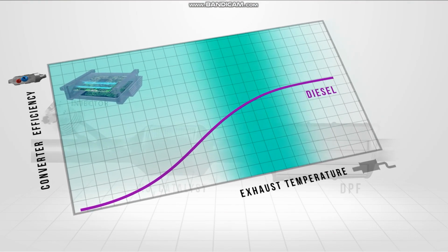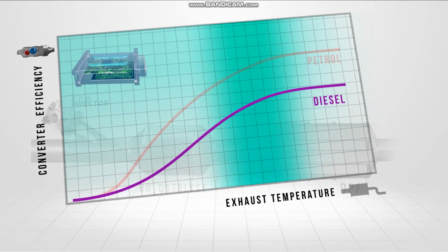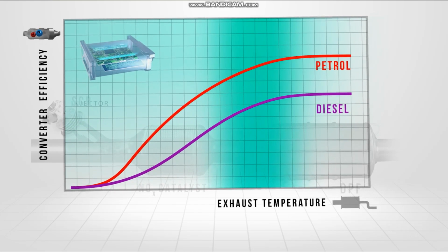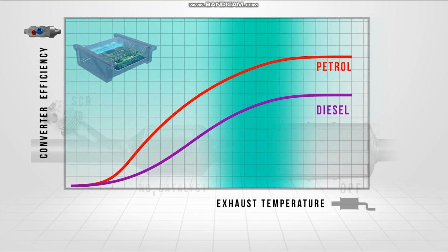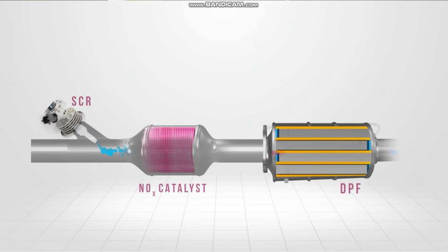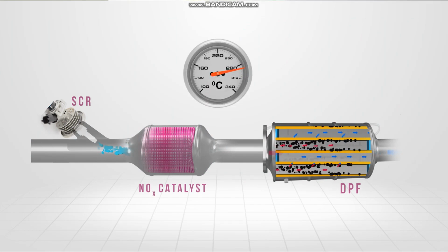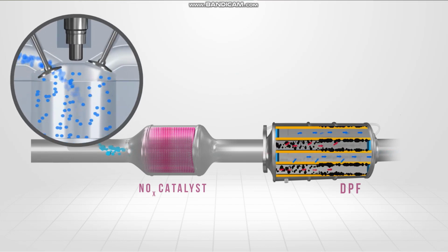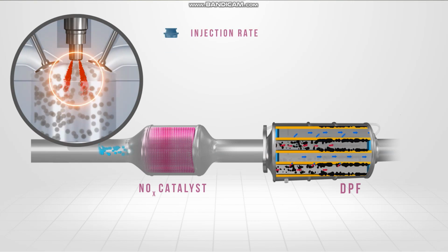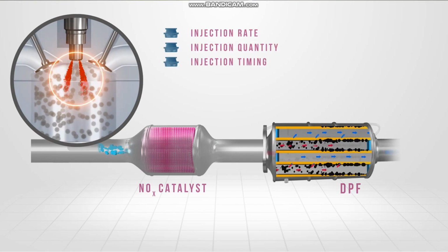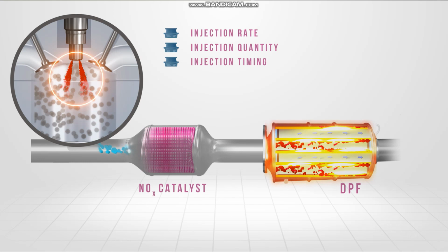While exhaust temperatures are considerably lower on diesels than the equivalent gasoline engine, strategies are still required by the engine management system to regulate catalyst temperature for an efficient control of emissions. These engines may also be fitted with additional exhaust after-treatment components, which require sufficient heat levels to operate and transition to regeneration modes. The ECM will control engine fueling using the injection rate, quantity, and timing to achieve a target exhaust gas temperature for a specific mode of operation. This in turn will change the operating temperature of the catalytic converter, which may be used as part of the exhaust after-treatment process.